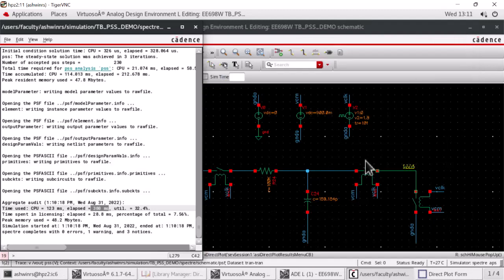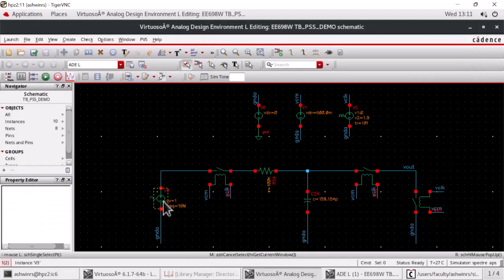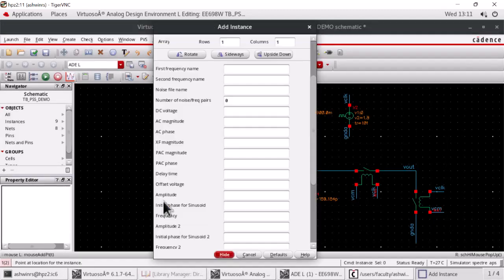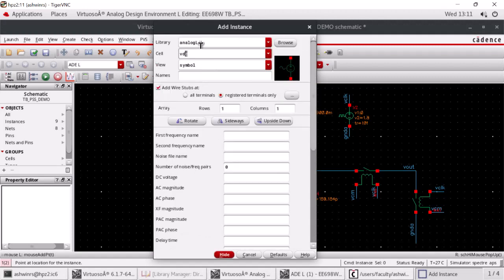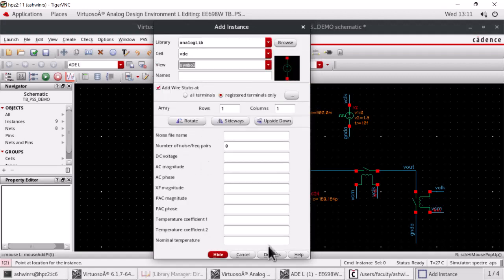Okay. So now let's actually look at the harmonic transfer functions, and for that I'll not give any input, everything is DC. So here I'll set the magnitude, this is basically for PXF, for finding the translation from F plus KFs to F, and if I say the magnitude is 1, it will apply a 1 volt sine and cos, right?